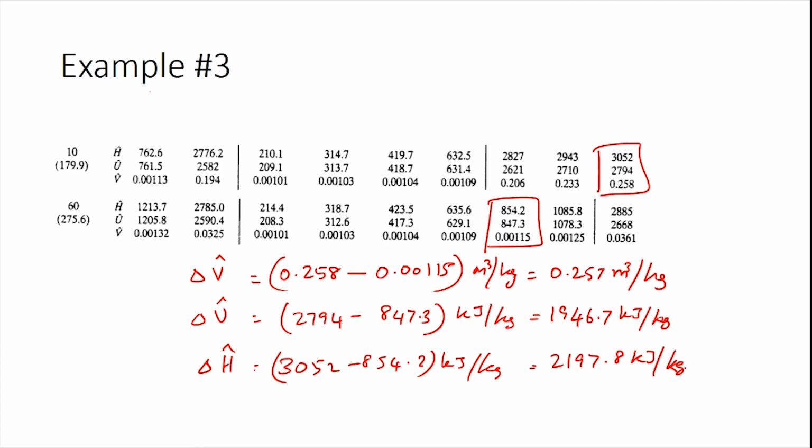the boiling point for the superheated steam. So, dew point would be the point at which condensation happens. So, here the superheated steam state is 300 degrees Celsius and 10 bar. So, going back to these values here, you can find the boiling point as 179.9 degrees Celsius, which is also the dew point or the point at which condensation would happen.